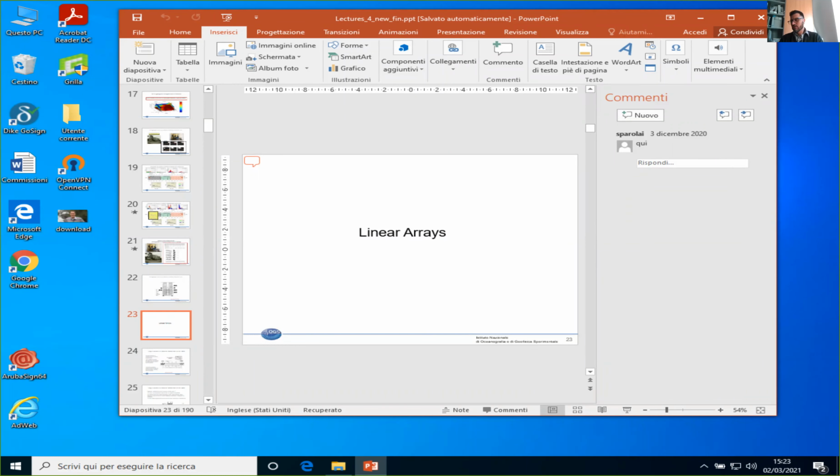So when you have a large ground motion, soil starts behaving non-linearly. So the response can also change significantly, even if in some ground motion parameters used in seismic hazard, sometimes the effect of nonlinearity is not so clear. So there is also a discussion, some of the guys who are here following lectures working in Orbesis are exactly dealing with this problem. How clear can this effect be? It depends strongly on the parameter that you analyze and the frequency content and so on. In the building it is the same for different reasons, of course, but the building response can also be completely different when you start having large shaking, nonlinearity, and then even worse when you start having damage to the structure at different levels. So this is a clearly different behavior.